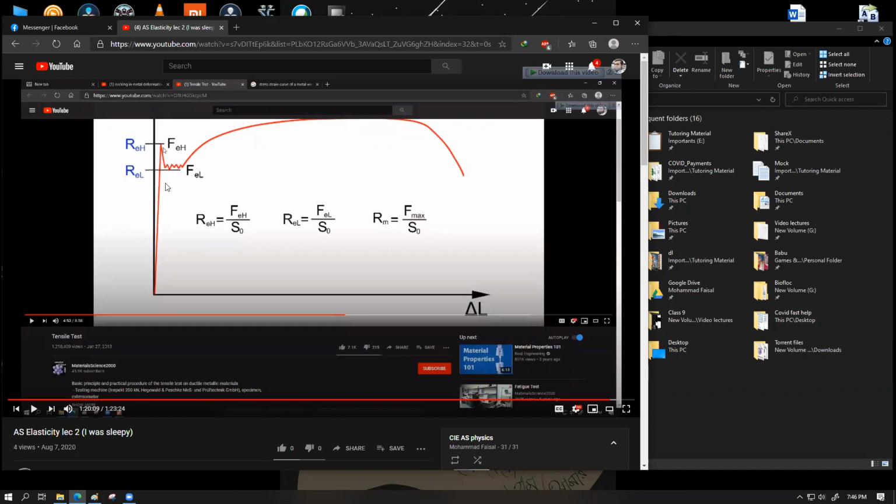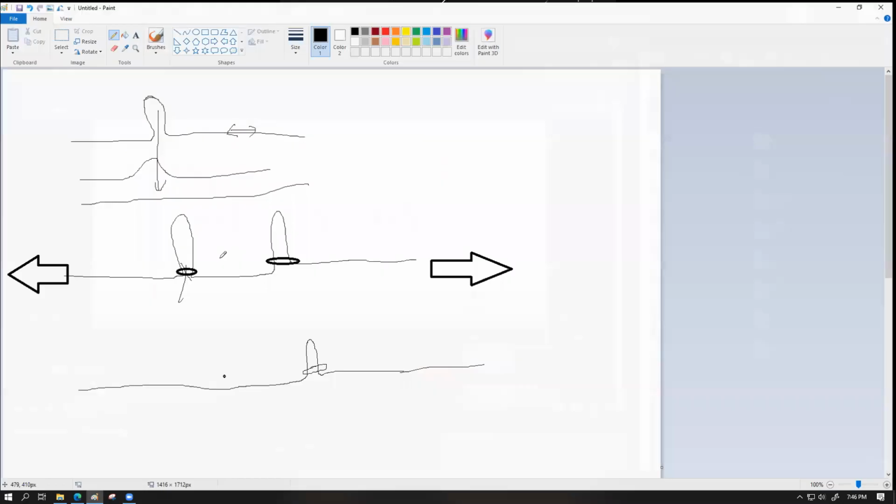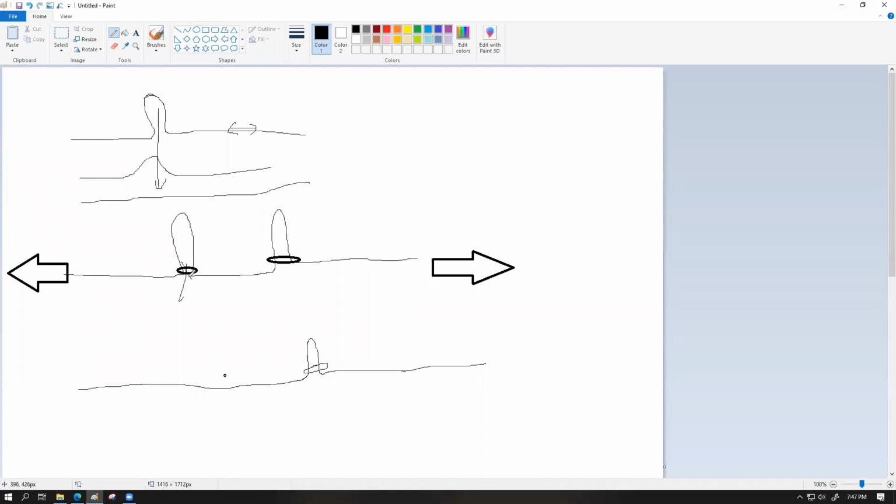Whenever the resistive force of the device reduces, the machine would be able to extend the object with a much smaller value of force. Think about the example that I'm trying to pull over here. Whenever this loop breaks apart, you have a very high amount of force which was required to break this loop, let's say. But for the small fraction of time when this loop would become elongated, would you require that exact amount of force to make this straight? No sir. So you would require a smaller amount of force. Your device can apply a really high amount of force, but since the material is not resisting that much force, the device would not be able to apply that much force onto this thing, because these two forces have to be equal.